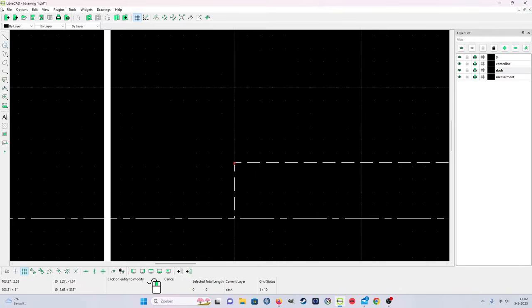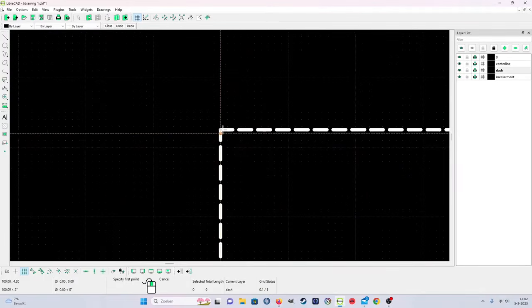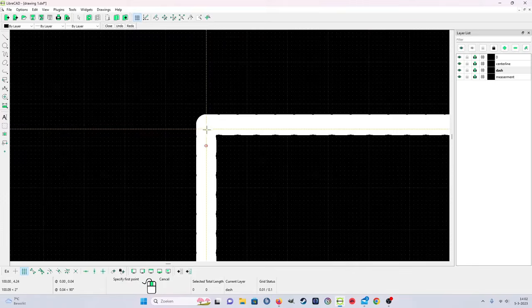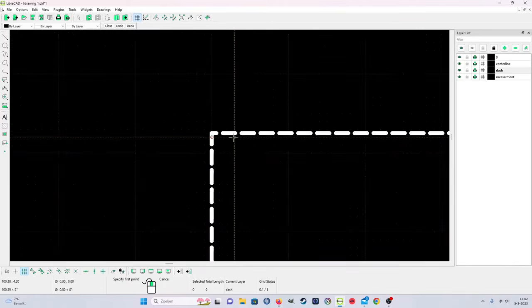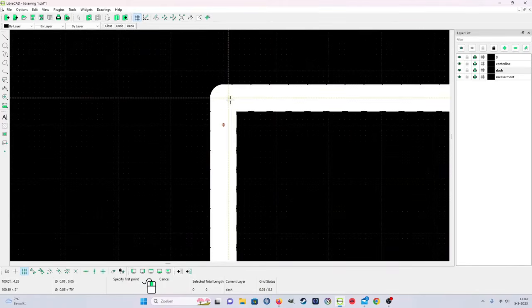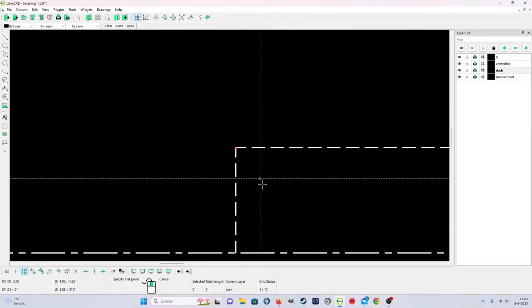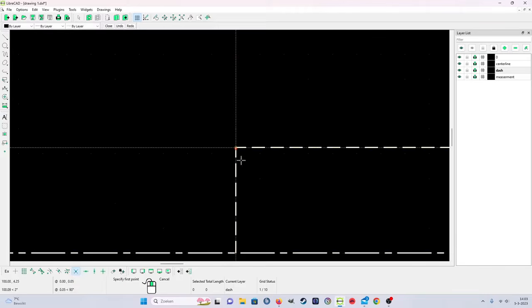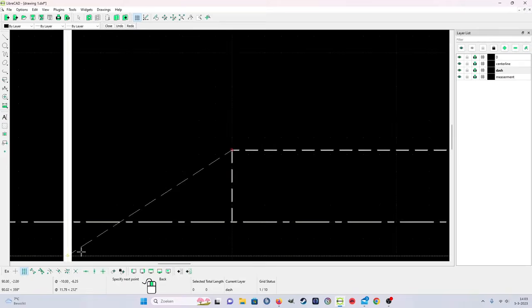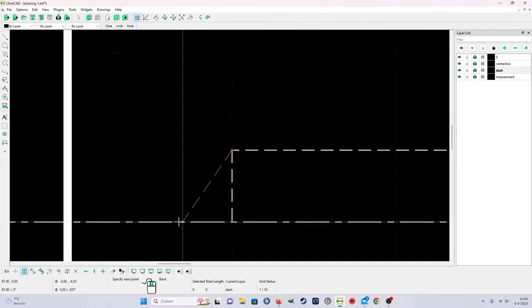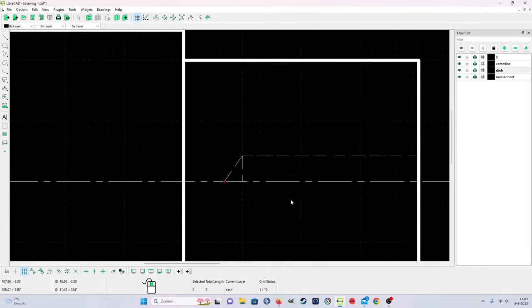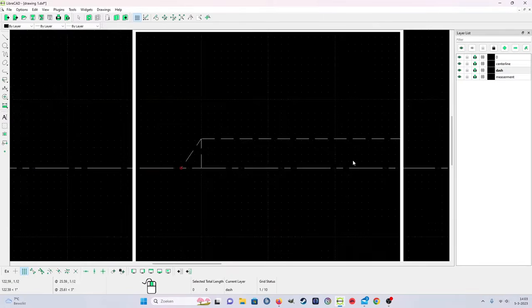Now I'm going to put the drilling point on. You see what I mean? I must zoom very far in now to get to the exact point. But if I do this again, and I do the snap, then it's going automatically to here. And when you have selected the point, put the snap off and put the grid on, and then you can put the point where you want it to have. So that's my drilling size.